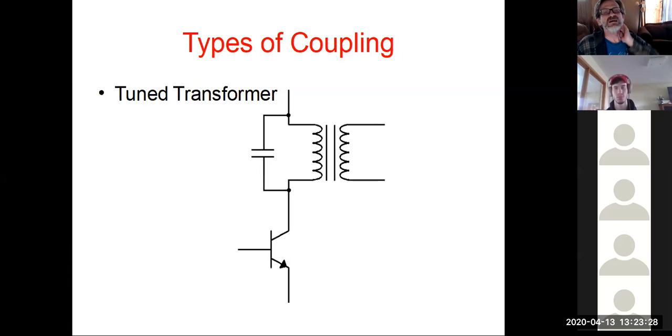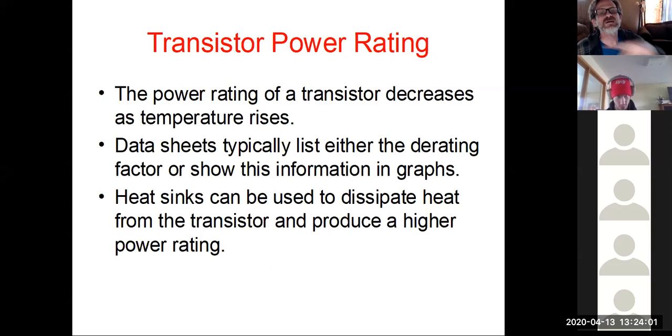Go ahead, Brenna. And then this is a tuned style where now it's an LC circuit or an LC filter. So you have that capacitor on that side, and it attempts to alleviate any kind of noise that might be in there, and then that would pass through and go to the transistor for amplification and then pass through, depending on our circuit setup. But those are pretty much the two types for using a transformer or inductor style, if you will. Go ahead and click us through.